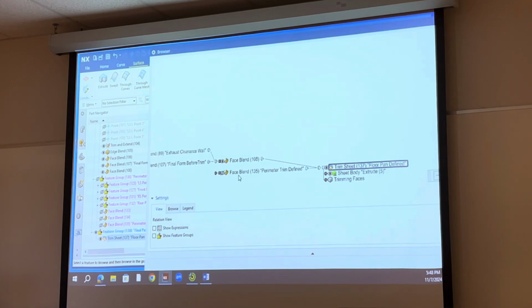So doing it the way I did, by default in NX, when you go back in time, make something the current feature, and you add another feature right after it, it inserts itself into the history. Just 2 minutes ago, this wasn't here. This guy was connected to that guy. But I went back in time to this, added this one, and it automatically inserts itself. I know I repeated that, but that's something you need to be aware of in NX. We haven't really dealt with that very much, but that's good to know. That's how you put things in after the fact.